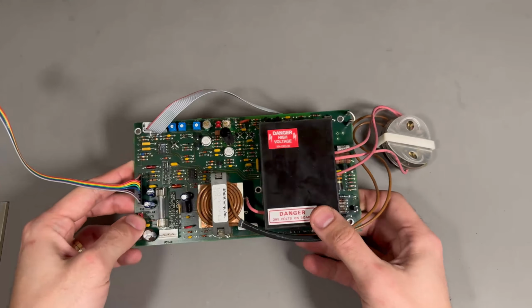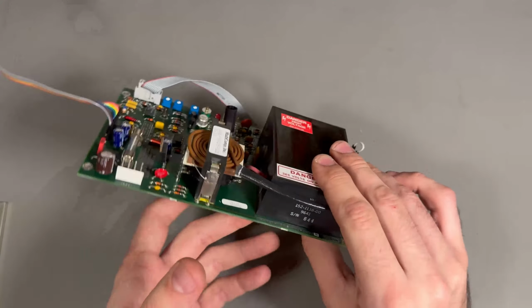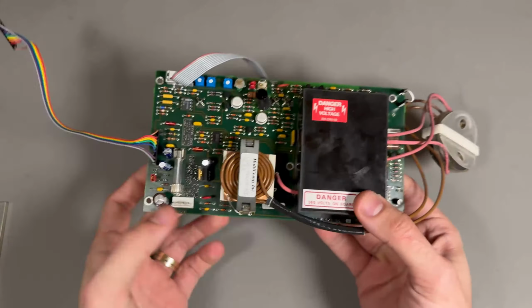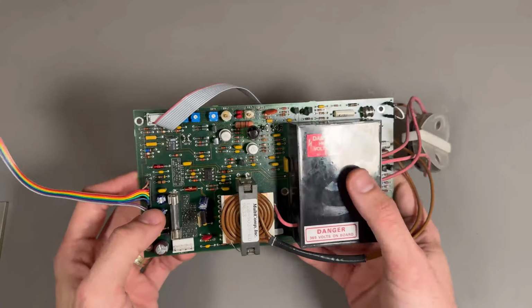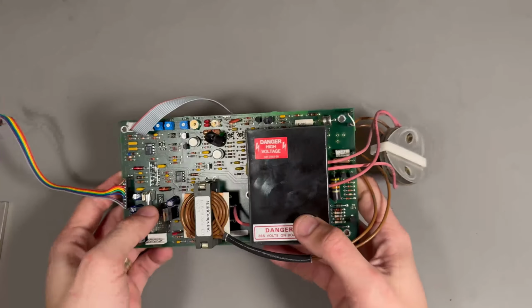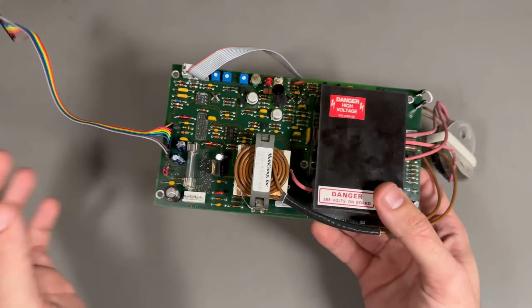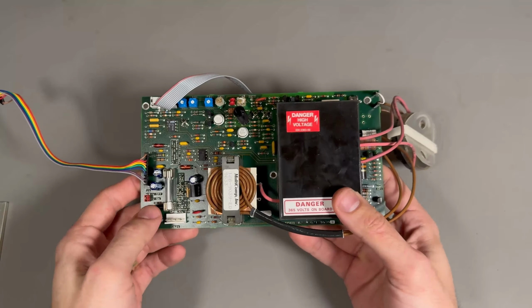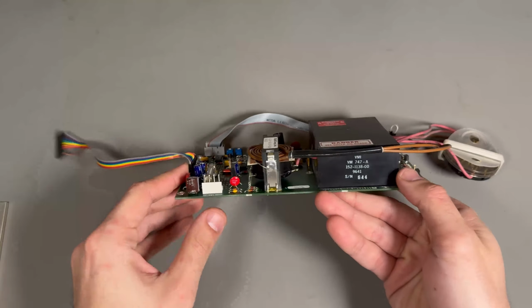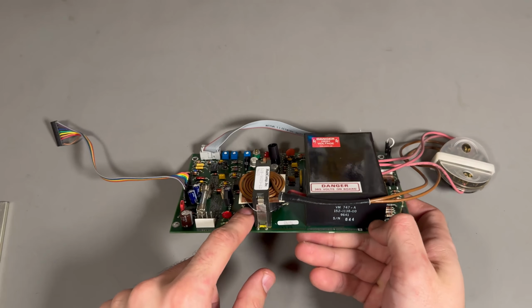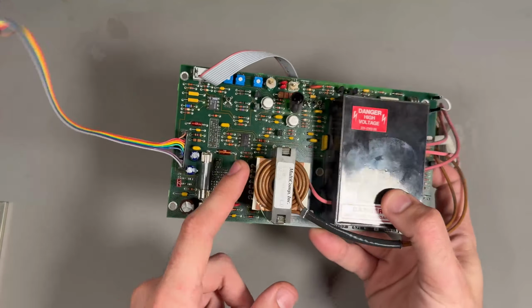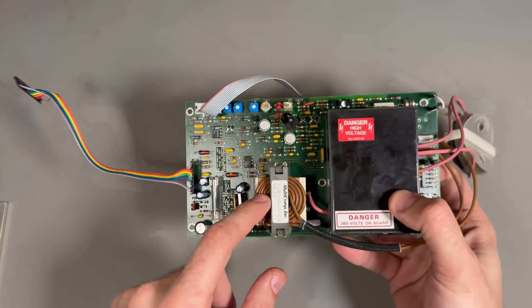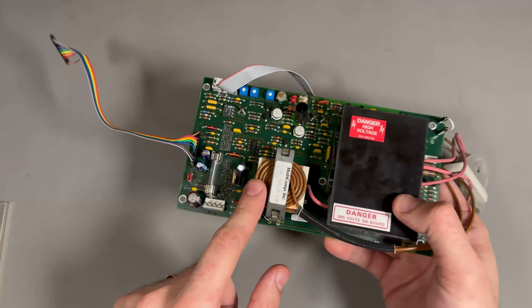And very impressive. This weighs a lot, so this brick is quite substantial. There's quite a lot of filtering, diodes, capacitors, a Cockcroft-Walton multiplier, something like that in there, because you need a very stable power supply for an oscilloscope high voltage. So yeah, and the transformer looks relatively familiar to the one in the 460 series, 400 series, basically the newer ones.